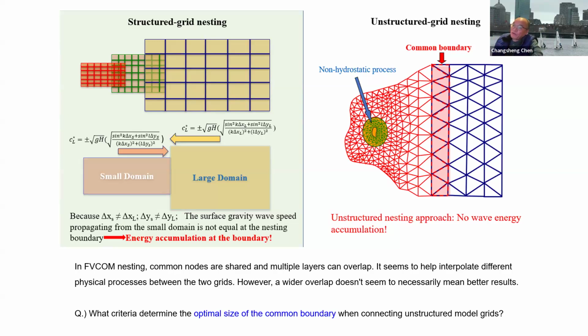They get internal wave reflection. If the water is non-stratified, barotropic, you don't worry, because with no stratification there is no sigma error. Sigma error is only caused by the density gradient, and the density gradient is not caused by the sea level.